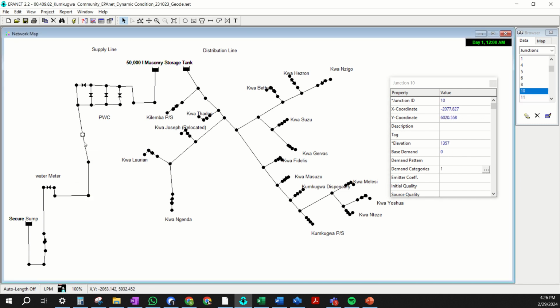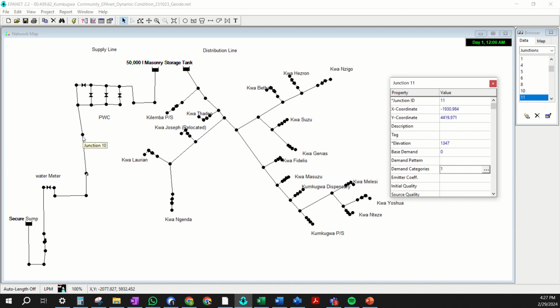It doesn't have to be perfect, but something close to help us understand what's a long pipe and what's a short pipe. So here we have 200 meters of PN16, 300 meters of PN12, 1,500 meters of PN10. I would combine these two pipes, but it's not necessary to do that. So I'll just lengthen these lines a little bit to make it a little more clear that they're longer pipelines.